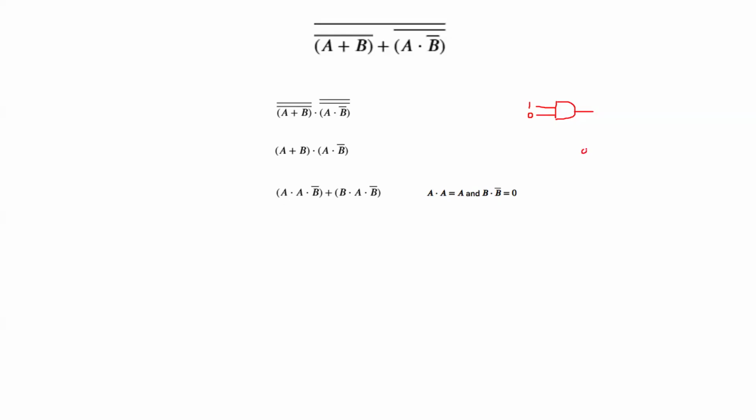See the truth table of an AND gate? 0, 0, 0, 1, 1, 0, 1, 1. These are the inputs, and here will be the outputs. Both of the inputs have to be on for the logic on the output to be 1. Otherwise, we get zeros here. So they will never be the same.